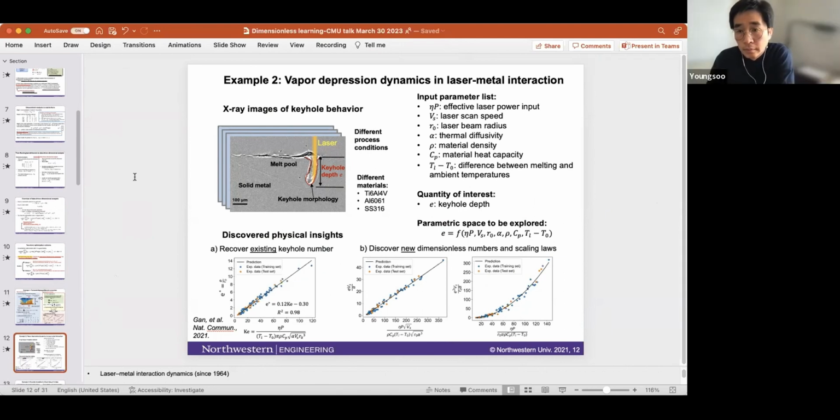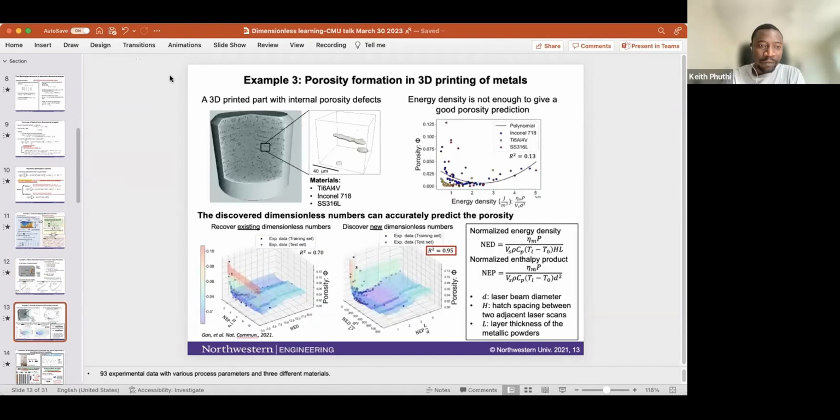Sounds good. Yeah, sorry, I have one question. On where you showed the improvement where the R squared goes from 0.7 to 0.9, I have two questions about that. What do you consider a bad R squared? How low does it have to be for you to say, okay, this is a very bad fit? And the second question is, what was added there is a d cubed over L cubed. Do you have some interpretation of that? It looks like a volume ratio of some sort. Have you dug into the physical meaning of that d cubed over L cubed?